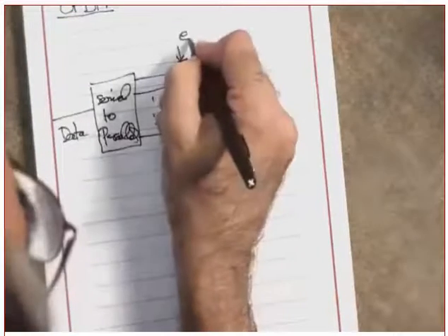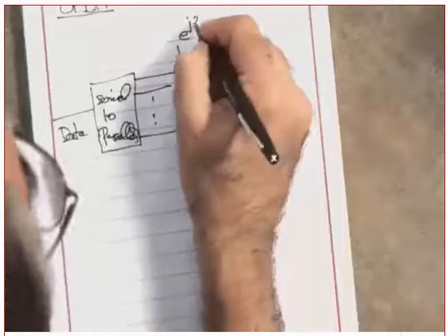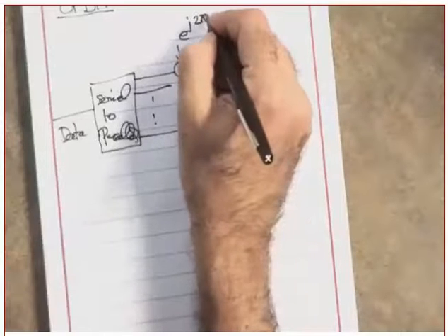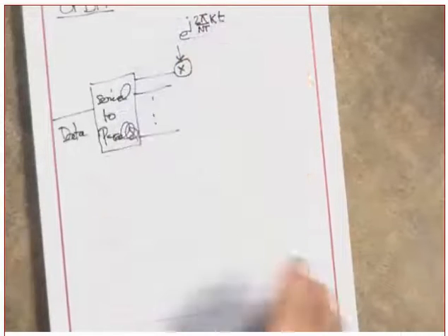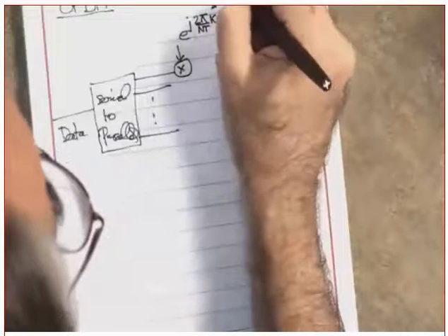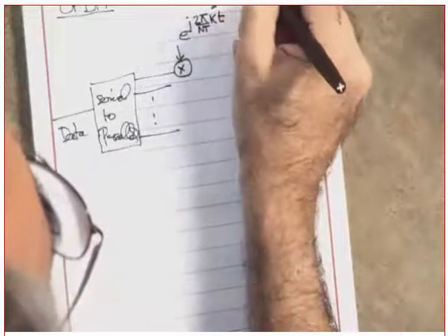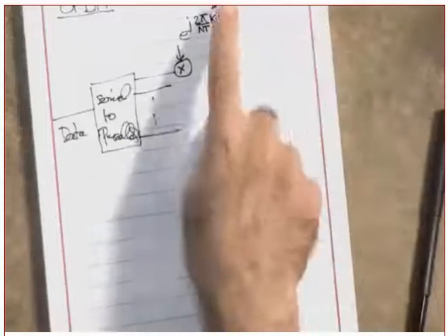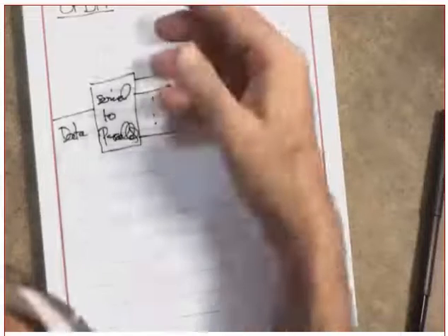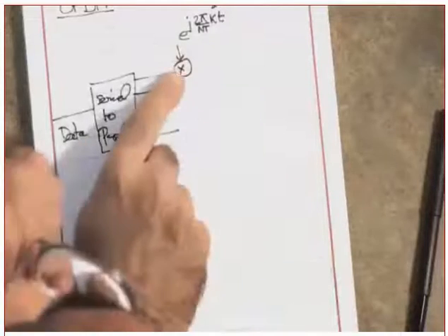So instead of saying that, I'm going to write this: e to the j 2 pi k t over N t, where k is equal to 0, 1, 2, all the way to N minus 1. What is the N here? It is the number of subcarriers.